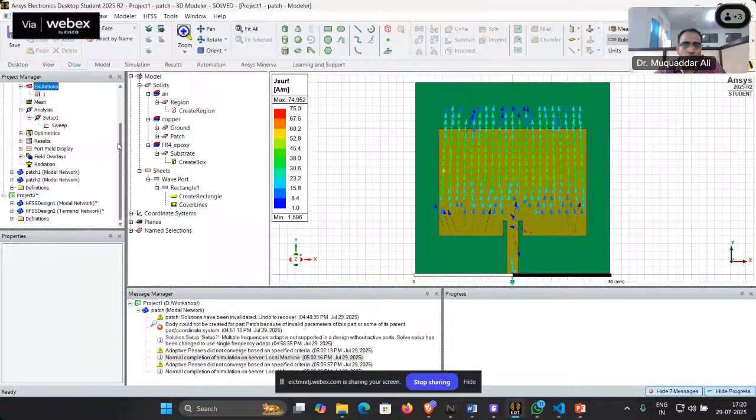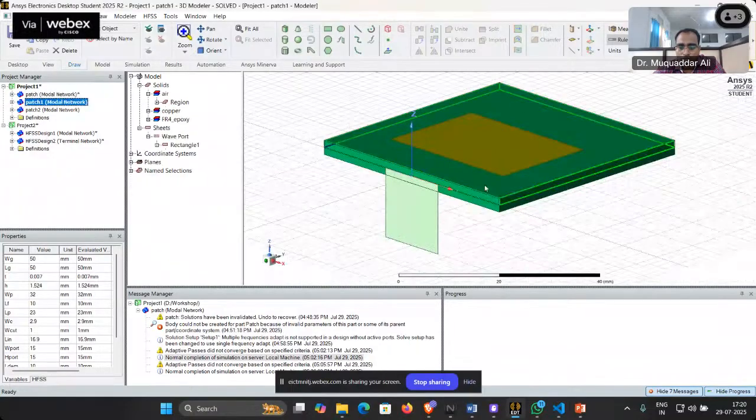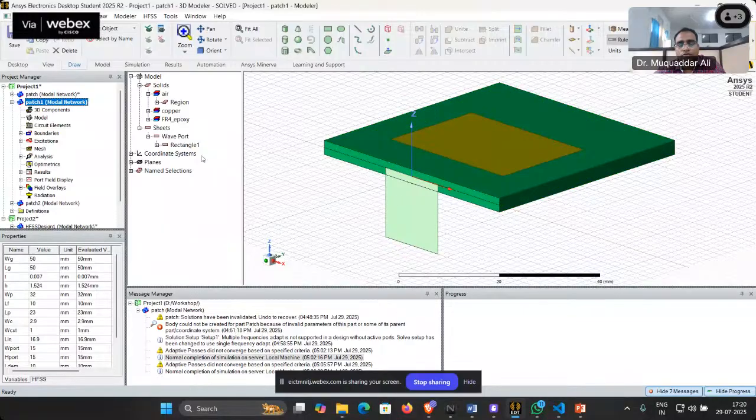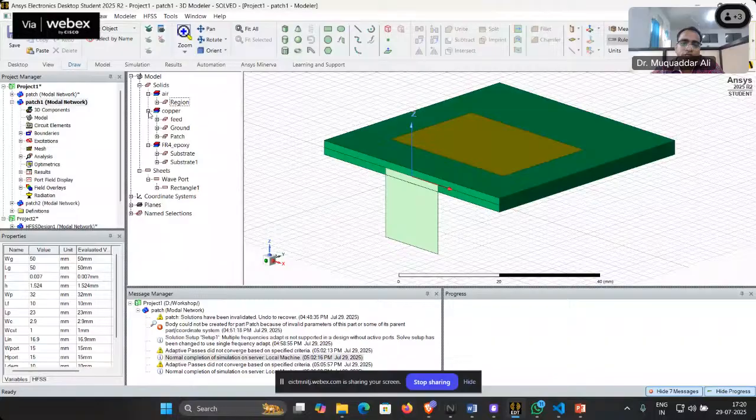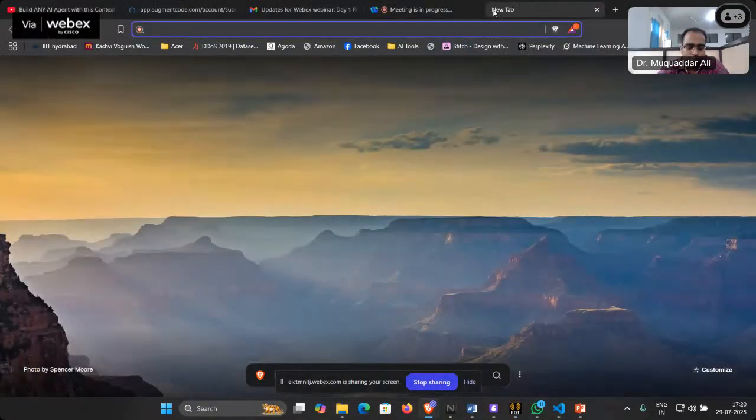So this is how you can design your antennas. Now we can have another design in which we use aperture coupling, but that I am giving as an exercise. There are four basic categories of feeding in microstrip antenna. One is direct feeding, that is coaxial feeding. Another one is microstrip feeding, and aperture coupling and proximity coupling. I am giving you some diagrams, some links to follow.